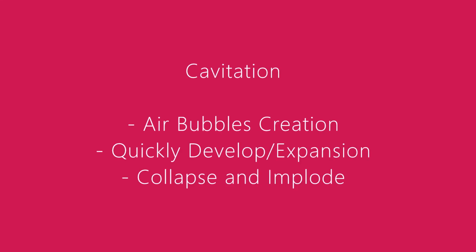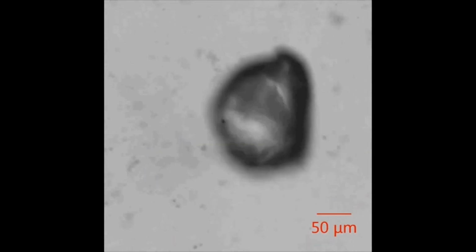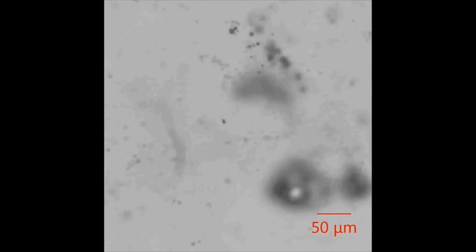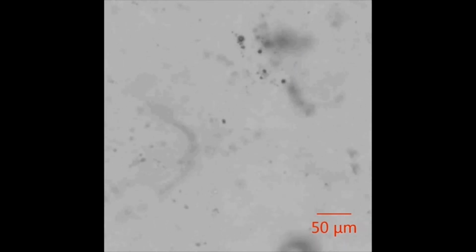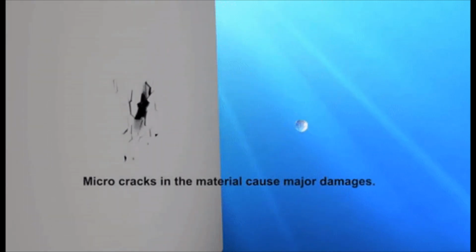Cavitation is the creation and collapse of the air bubbles in a fluid where the bubbles quickly develop around the impeller's axis. When the bubbles pass from the middle of the impeller to the outer edges, the centrifugal force creates high pressure, causing these bubbles to quickly collapse or implode with great force. The forces generated by the implosion of those bubbles will cause huge vibration and pitting effect to the impeller. Ultimately, all this impact will cause major damages to the pump impeller, body and motor.